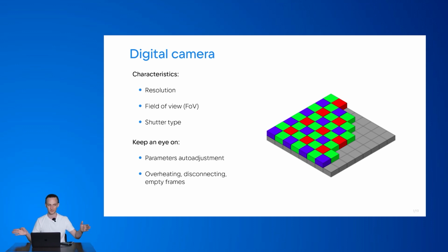And the horizontal field of view is more important than vertical, really, because we don't that often look at objects that are somewhere just above us in the sky. And typically the horizontal field of view, this horizontal angle, is much bigger. Some cameras have the diagonal field of view specified in their documentation or in the short form of their documentation. This is a little trick that presents the camera as if it's better than it is in terms of the field of view.